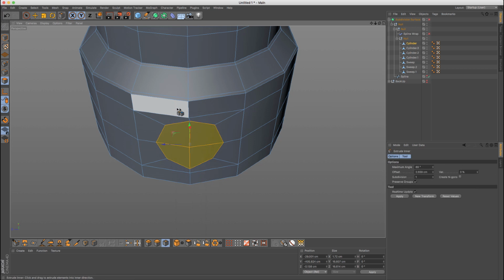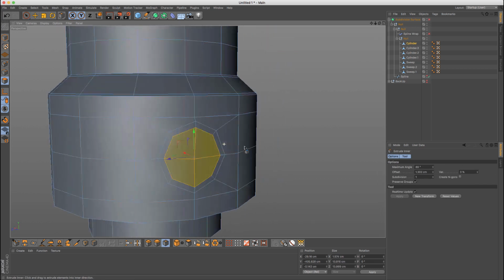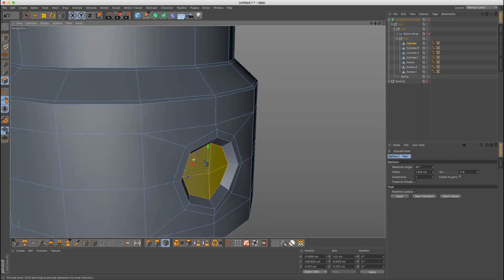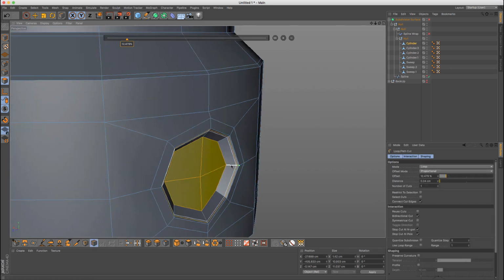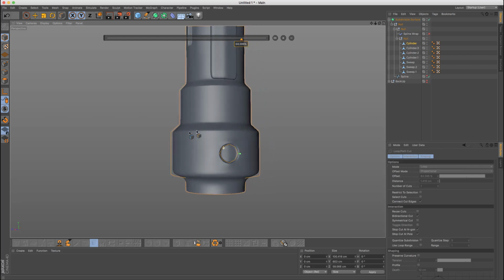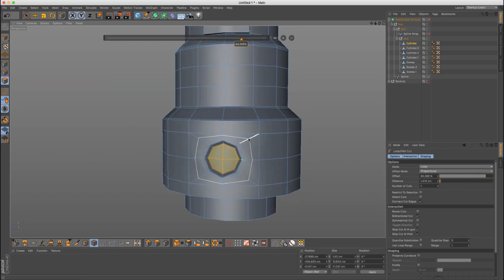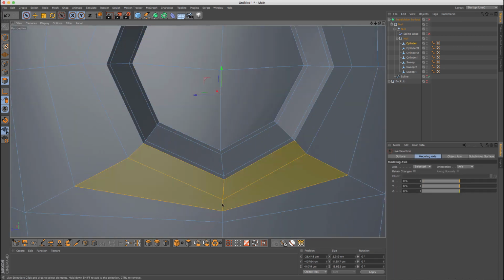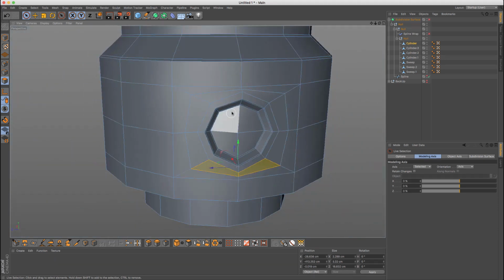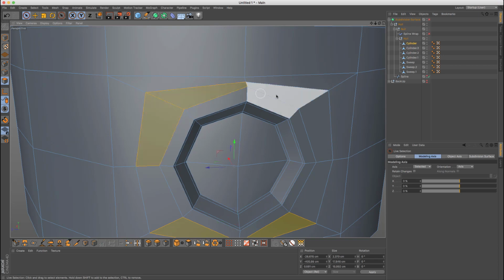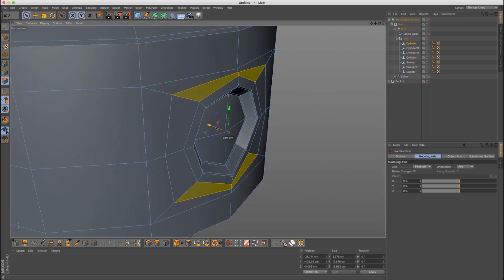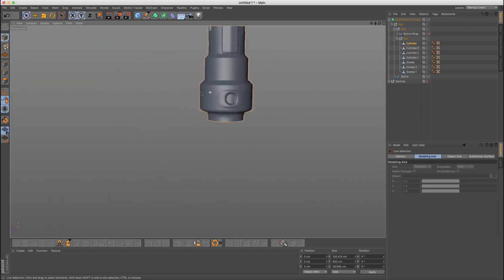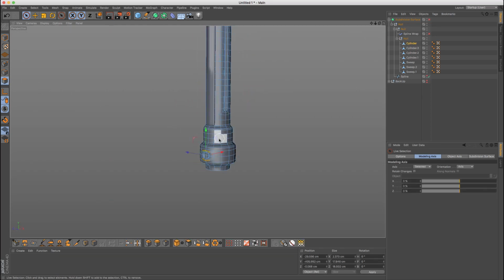And now we can go and extrude once, twice, push in just to break that surface, and I'll do a small extrusion, and then we can just add a few cuts here and here just to break that surface. And let's add another edge loop here. And also sometimes what I like to do is just select, let's say, this part, or then also this part, and we can kind of push it outwards just to create this little surface distortion, something like that.